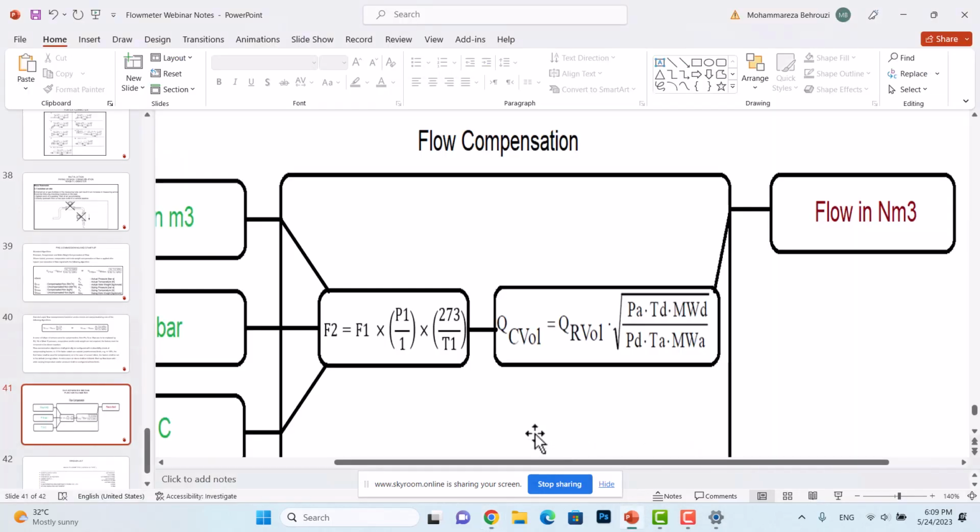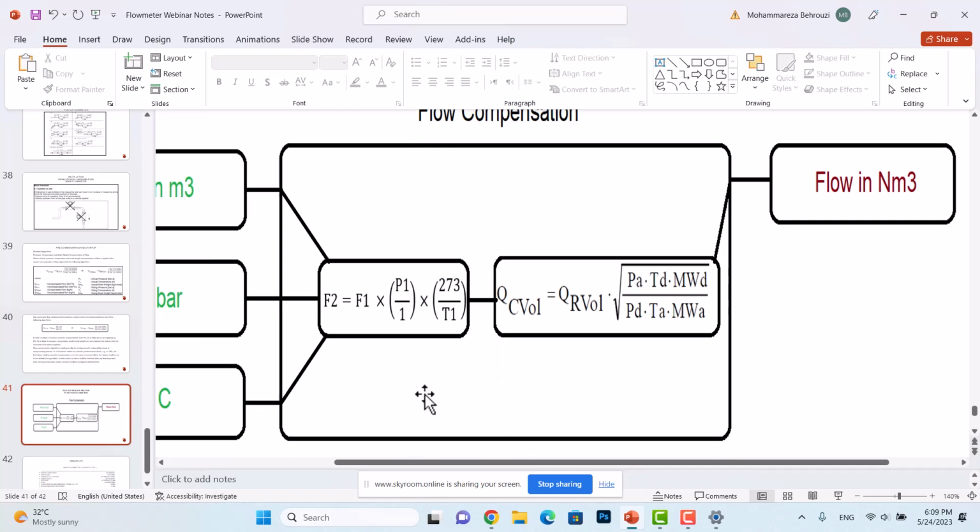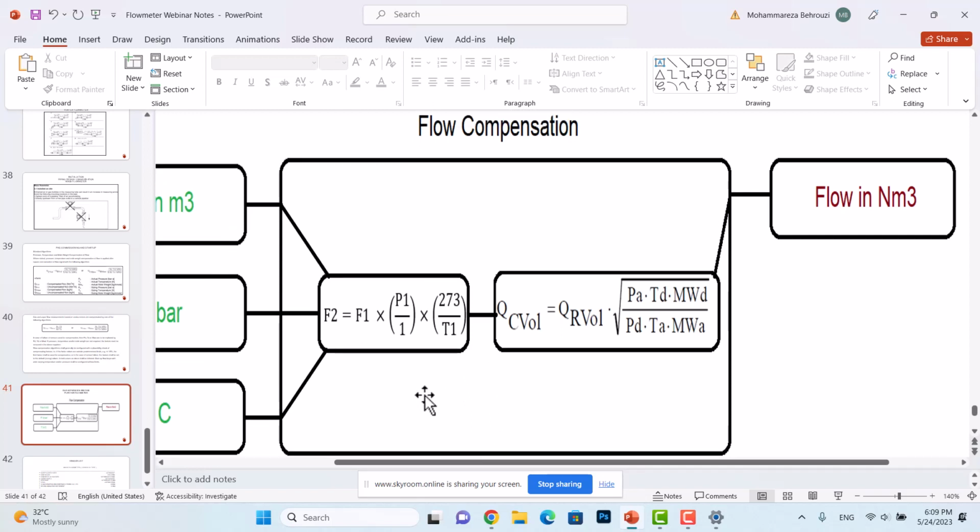we receive our plant air. Sometimes we need plant air for cooling down some equipment or for any kind of reasons. We receive the plant air from the nearby company, but at startup, the value indicated by our flow meter was not the same as the value indicated by their flow meter. Their flow meter was Coriolis type, our flow meter was vortex type, because as I stated, in battery limit we can use Coriolis or vortex type for fluids, and since the plant air is clean, we can use vortex type.